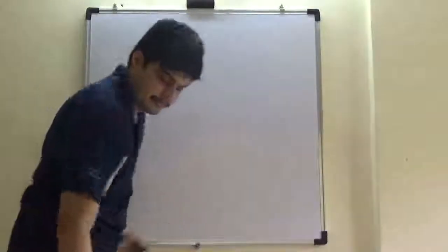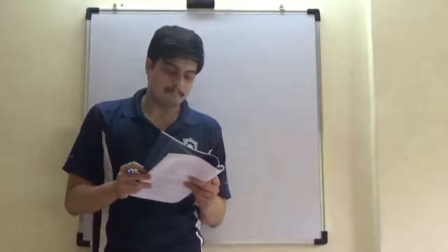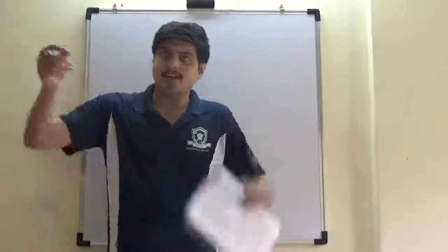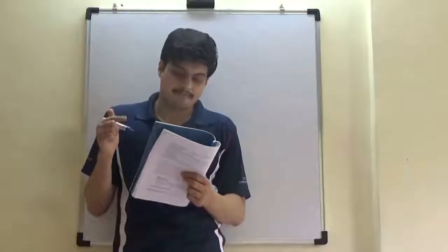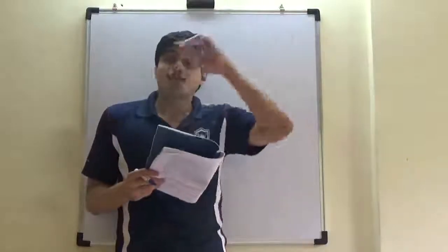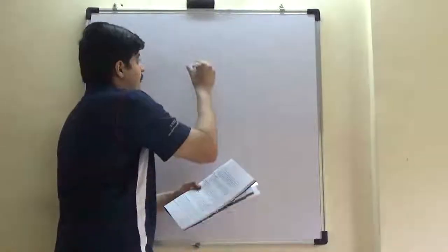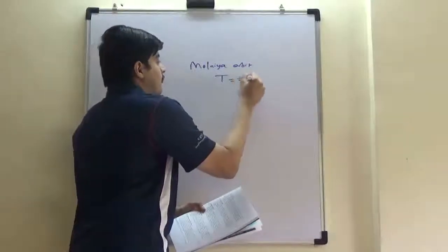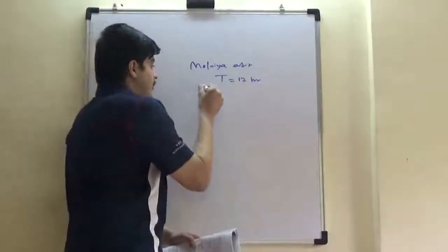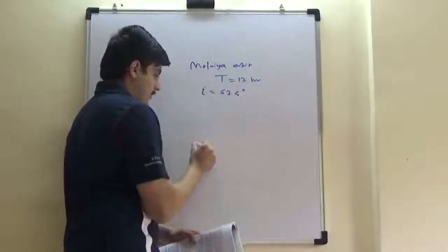That's the whole message. Now, in orbital mechanics, extremely important points to remember are geostationary orbits, where the satellite appears to be steady because it is in the equatorial plane. Geosynchronous orbits are circular orbits having a 24-hour time period. Polar orbits, 90-degree inclination, we have seen. Molniya orbits, these are something very important. Molniya orbits have a time period of 12 hours, and inclination i of 63.4 degrees.